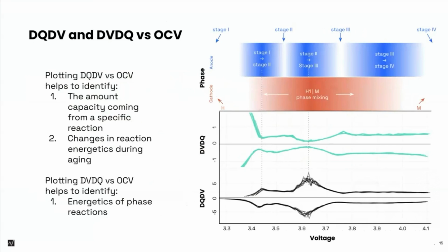As you get really good at looking at these, you can understand exactly what's going on. I can look at a lot of these systems now and tell, oh, this looks like a low nickel content material and they're using a graphite anode, or maybe they have some silicon. So as you get more and more familiar, you don't necessarily have to do peak fitting or anything like that to understand and tell the chemistry. You can see and understand by just looking at the general shape of the curve.